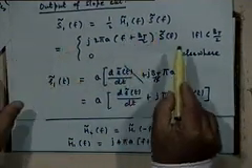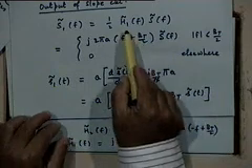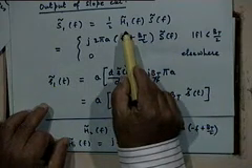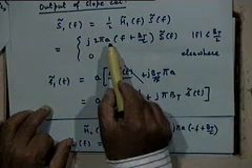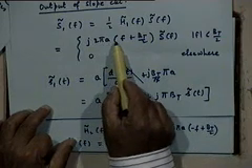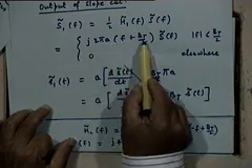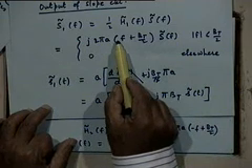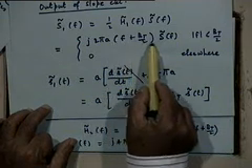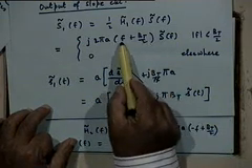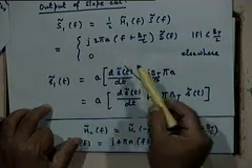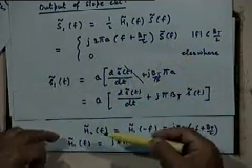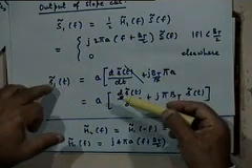So, everything remains the same, except that H1 tilde f will get replaced with H2 tilde f, right. So, what will happen? Instead of j2 pi a times f plus bt by 2, you will have j2 pi a times minus f plus bt by 2, right. This f will get replaced with minus f, and if you go to the time domain, which was the next step,